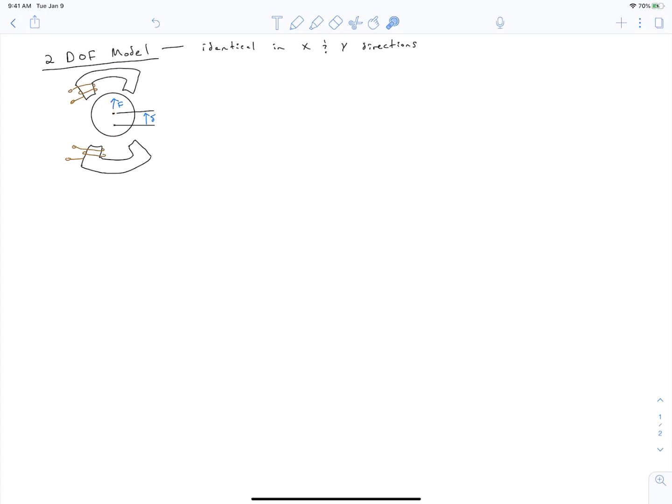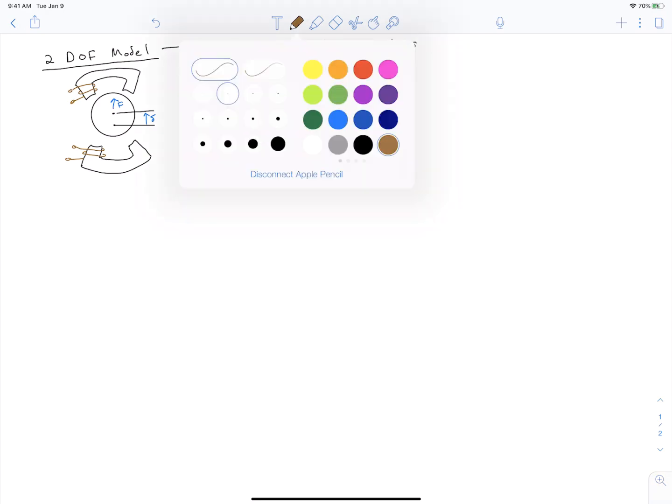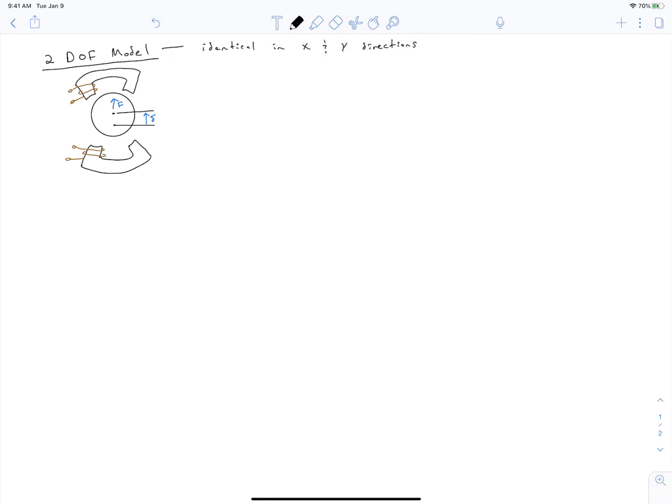And so the way I've drawn it right now is that it's currently already moved vertically by an amount delta from its nominal or centered position. And I've labeled our force vector as being vertical. So we're now going to start writing out the equations that we'll use to get our governing differential equation and our transfer function. First, we use the equation of motion, which is that the force that's acting on the shaft is going to be equal to mass times our acceleration.